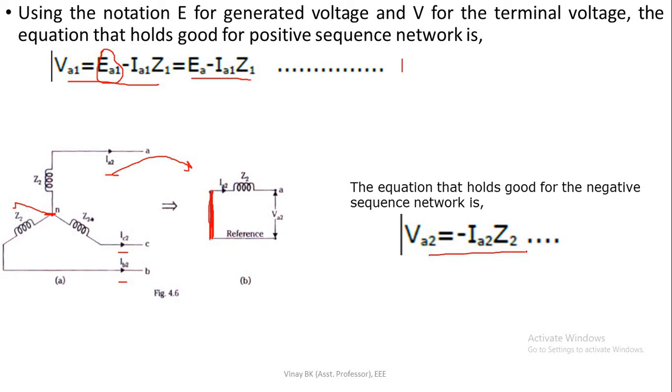It is known that the phase sequence of negative sequence current is opposite to that of positive sequence current. With a flow of negative sequence currents in the stator, a rotating field is created which rotates in the opposite direction to the positive sequence field, therefore at double synchronous speed with respect to the rotor.